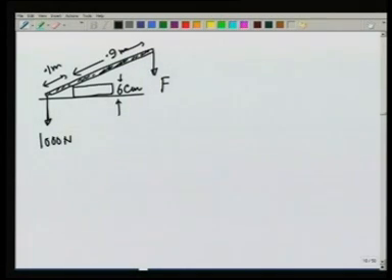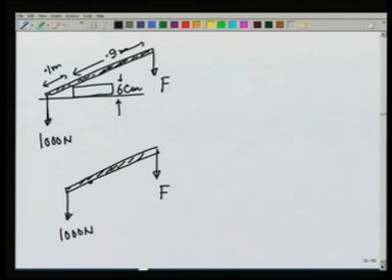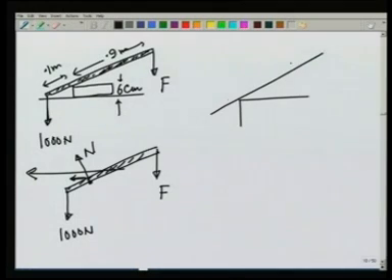What all would happen? Suppose initially I ignore the friction between the brick and the rod, then you can see that on the rod the forces that we are applying are number 1, the force downwards, number 2, the force downwards because of this load of 1000 newtons, and at this point the brick is going to apply a force perpendicular to the rod in this direction. You can see right away, if there is no friction, this N is going to have a horizontal component that is not balanced. So, the rod is going to have a tendency to move this way. In order that the rod does not move, there should also be a frictional force between the rod and the brick. So, we are going to assume that there is a sufficient frictional force that prevents the slipping to the left.